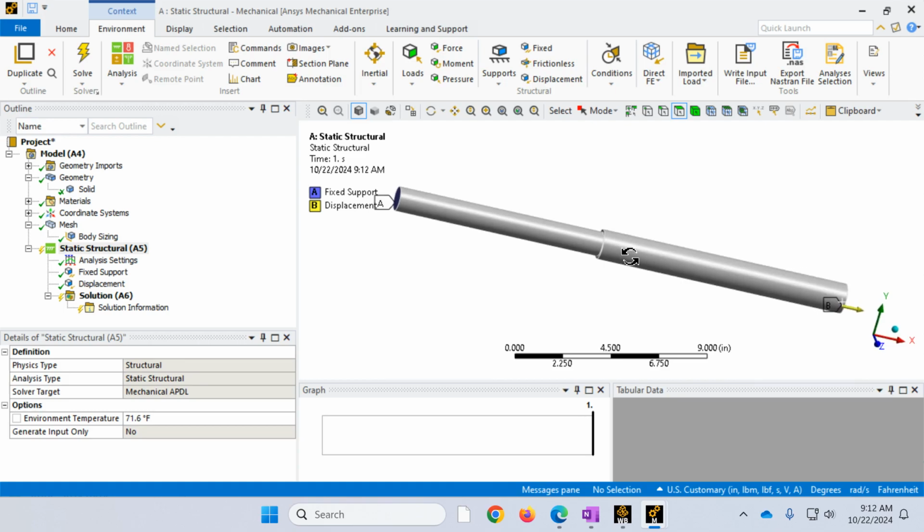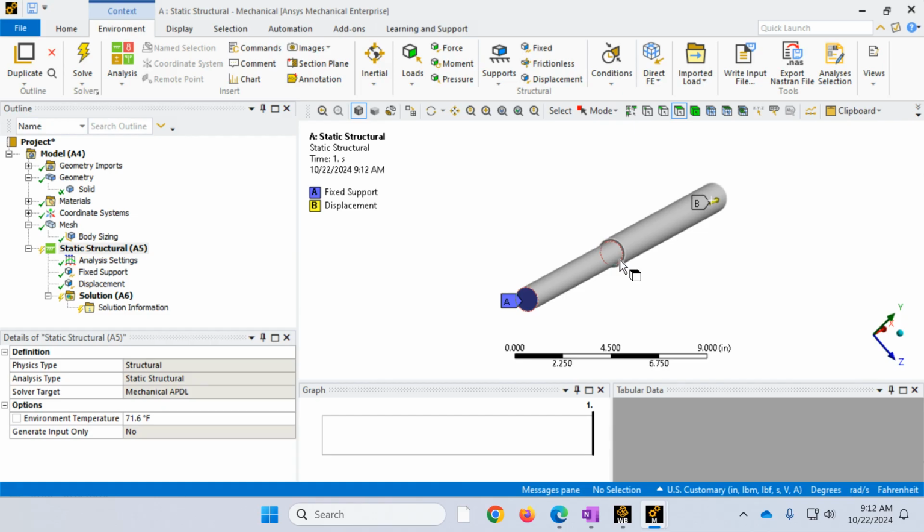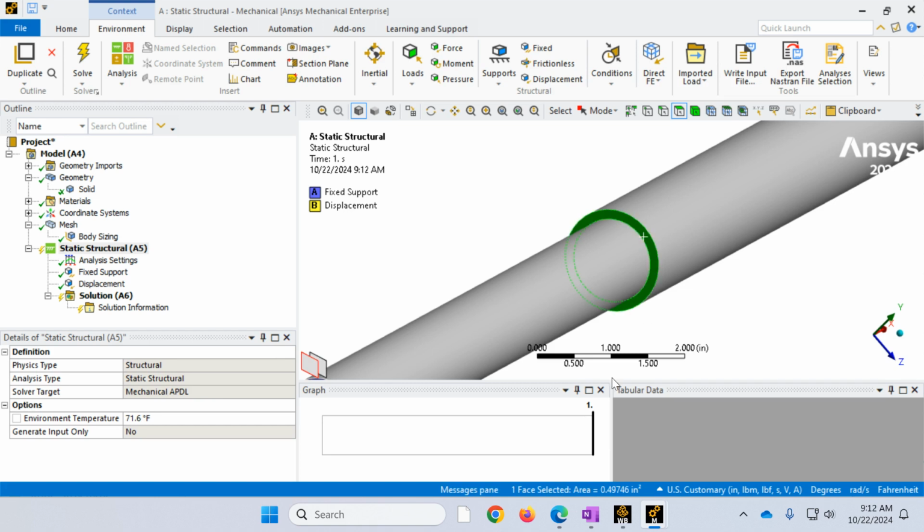Now, in real life, when you have a problem like this, you need to have a flange or a surface to load your part. So in this case, I'm going to use that face that I'm highlighting in green to apply my 10 kip load, 10,000 pounds. Because this is all symmetric, like a circular section here, the resultant is going to be going through the axis. It is not applied on the axis, it's applied to that outer surface, but the resultant is going to go to the axis.